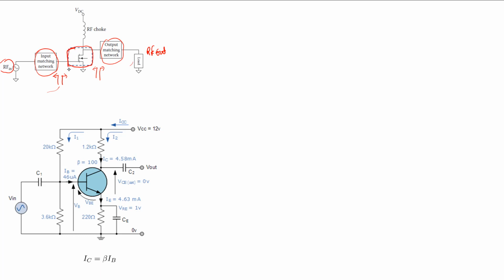But within the amplifier itself, the key element is going to be a transistor that is going to convert the input RF power into a certain output RF power, which is higher than the input. The extra power that is needed comes from essentially converting DC power. There is a DC power that is being utilized to boost the input power up to a certain output power.